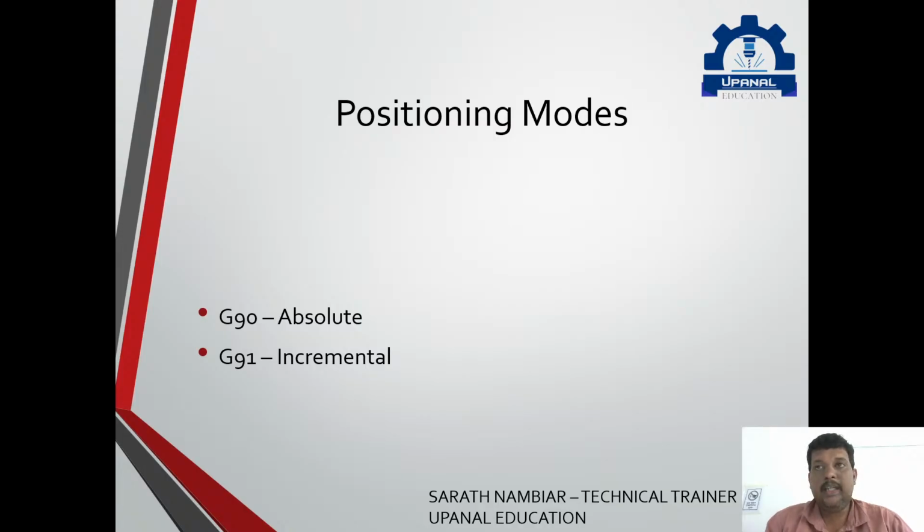But if I put absolute incremental value with absolute code, this drawing will completely change. What will happen? It will go into another complete dimension. I will be explaining it in the next class with a drawing which will be very understanding. Okay, now just understand this much. Absolute is from a fixed point and incremental will be from the previous point. From the previous point, the next value will be taken.